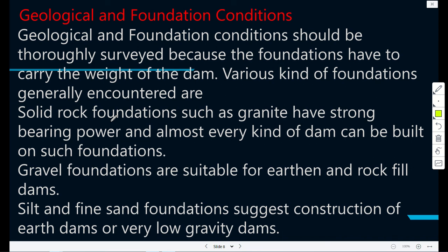So you need, for example, to map the geological condition of the dam foundation. You have to scan and know exactly whether there are faults, or whether the place is prone to earthquake, exactly how many faults, and you have to take measures to seal each and every one. Actually, areas of natural phenomena like earthquakes or faults need to be avoided altogether unless you have no other choice.